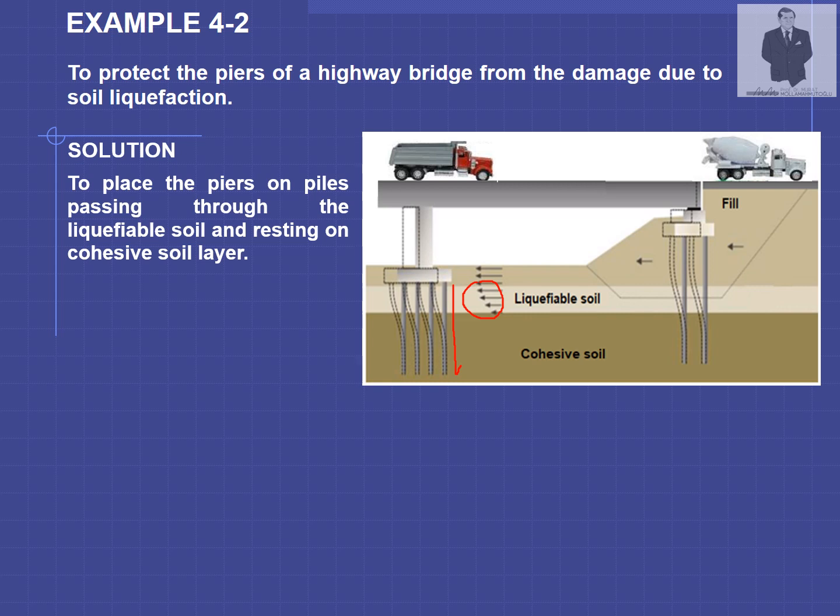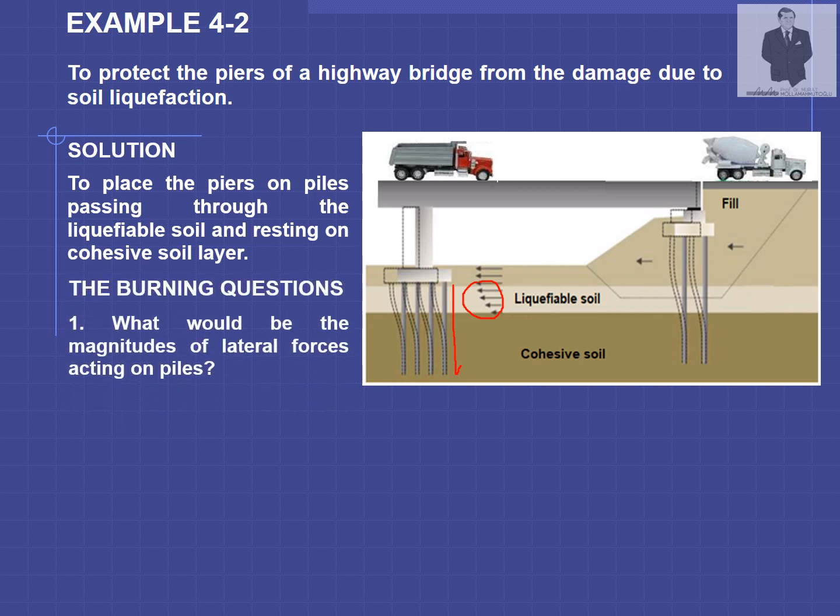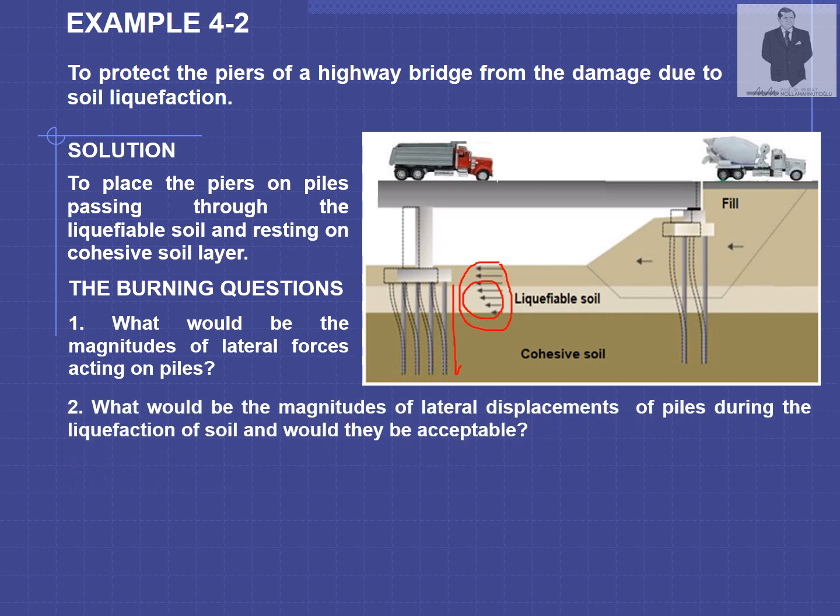The important questions that had to be answered by the geotechnical engineer were as follows. The first question, what would be the magnitudes of lateral forces acting on piles, especially during liquefaction as illustrated here? The second question, what would be the magnitudes of lateral displacements of piles during soil liquefaction, and would they be acceptable?